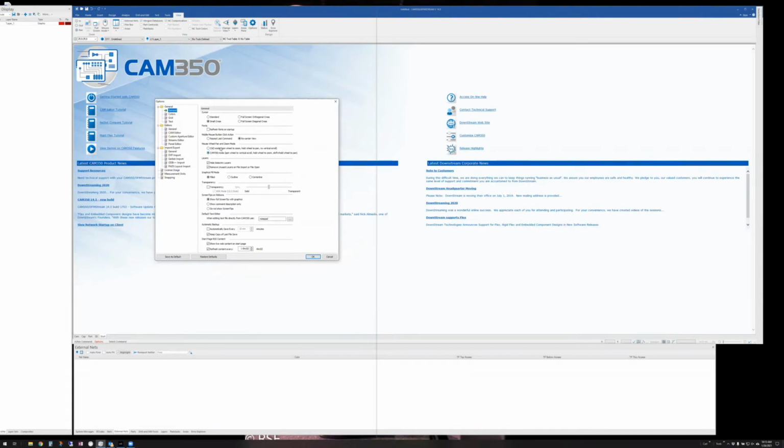So we put in an additional mouse mode if you prefer that other way of doing things, the way CAD systems do. When you bring in ODB or 2581, those formats now support dielectric layers. So you'll see those in your layer display table. Well, if you don't want to see them, you can turn them off here under Hide Dielectric Layers. Okay, and there's a few more controls to that.